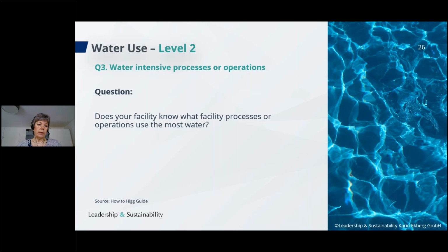So as a first step, you can map out your production processes together with, for instance, a site process flow diagram with identification of where usage is metered or can be estimated. And this can involve that you list all your equipment on the site that uses water and then identify through meters, quick tests, or estimates how much water each item on the list uses.